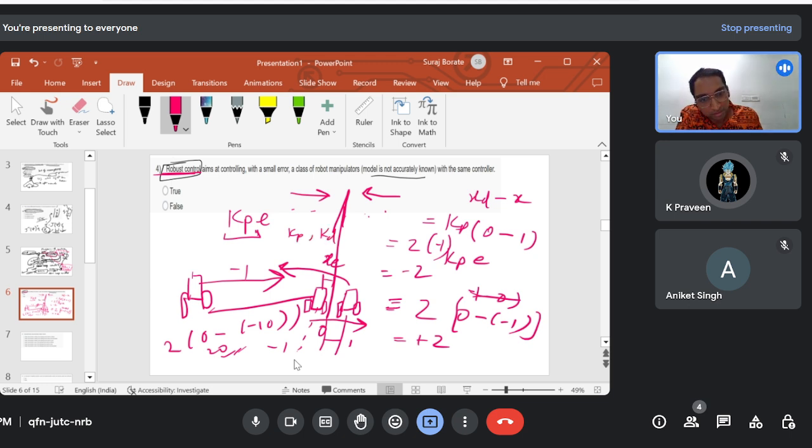Now what happens is, there are some disturbances that are stopping the robot from reaching the desired position. There's friction or some wind. Then in that case, you will require this Kp to be even higher. So I'm giving you the intuition. Suppose 20 was required to reach here, but there are some disturbances. So you need Kp gains to be higher.